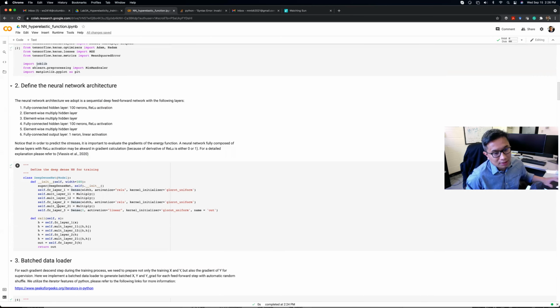One important thing is that in this particular case, the data set is only generated for one microstructure. And in the training process, two problems are merged together: the problem of composing an energy functional, and the inverse problem of identifying the material parameters. In this machine learning case, there is no material parameter to identify, because we are simply trying to generate a model for one particular microstructure. This is also an important difference between writing a neural network energy functional and a handcrafted model. In a handcrafted model, you are never going to write one single model for one microstructure.